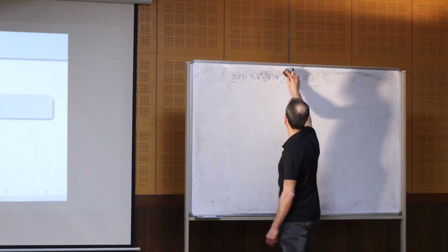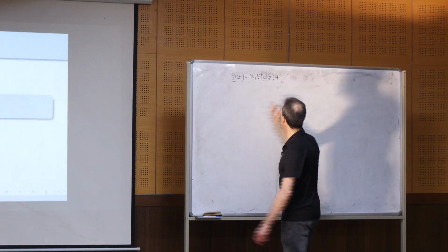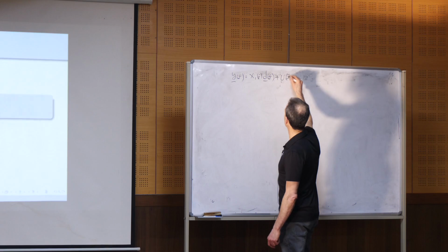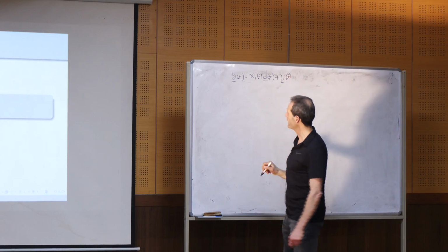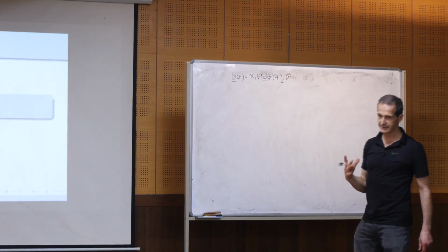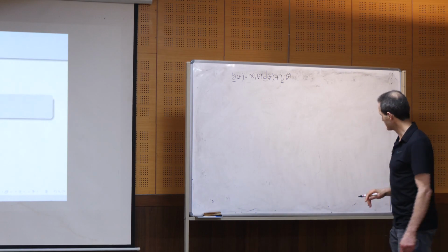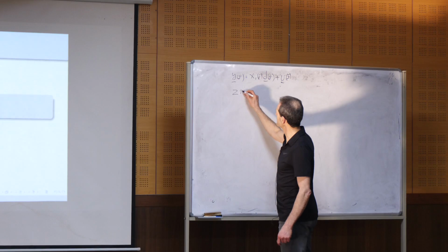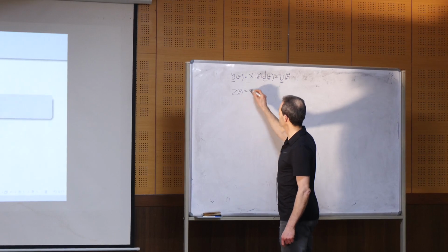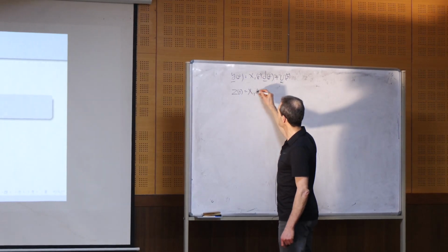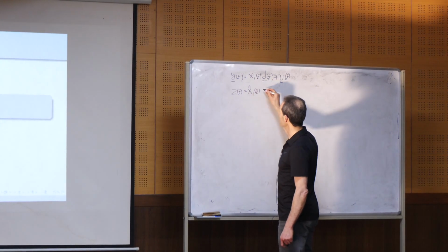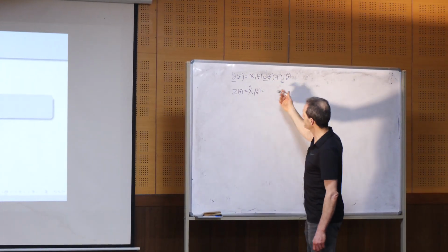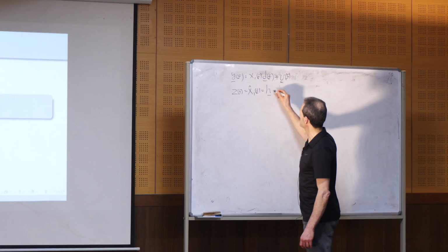This is the vector of noise for the frequency f in all the M sensors, okay? And then we try to find an estimate of the desired signal in the reference channel, in the reference sensor, by obtaining a linear filter that looks like this.